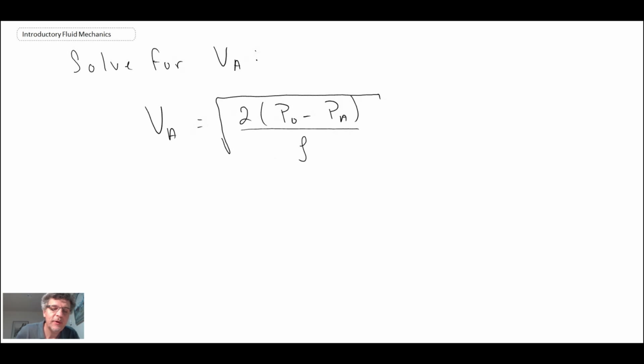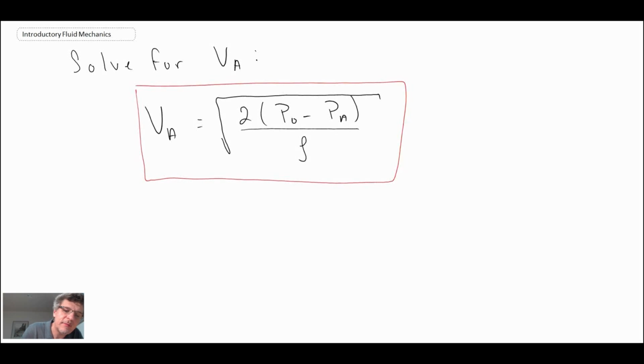And we end up with this equation here. So what does this tell us? That tells us that with Bernoulli's equation, if we are able to measure this pressure for the stagnation streamline, and if we're also able to measure PA, which was what we call the static pressure, and usually I'll show you a thing called the pitot tube next, and we do that by making a measurement at this location and knowing the density of whatever fluid we're dealing with.